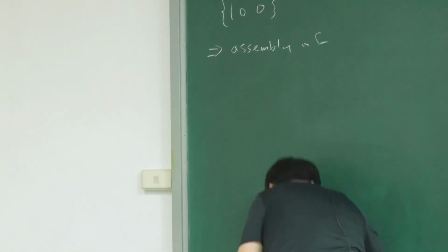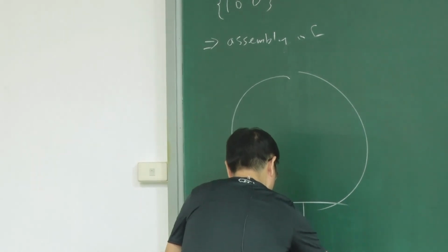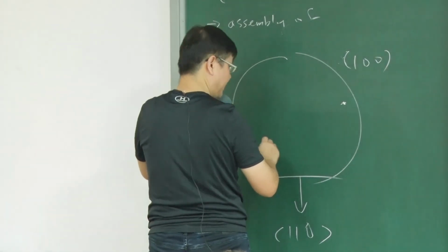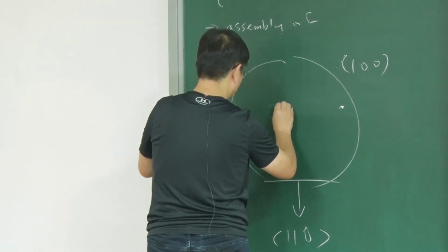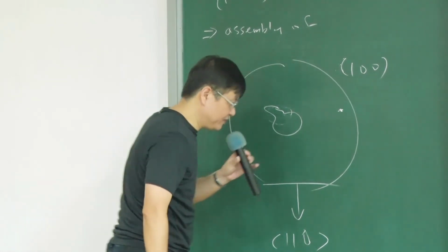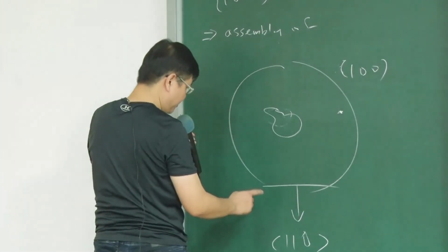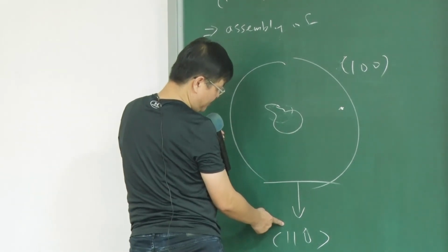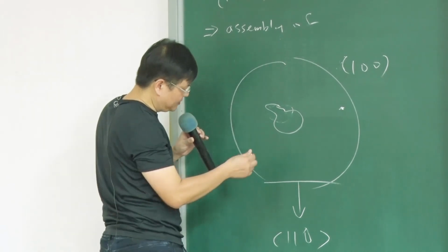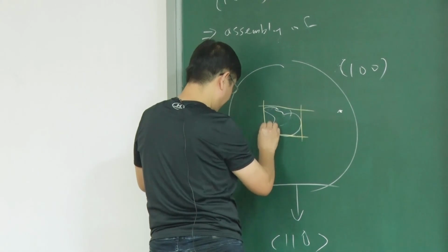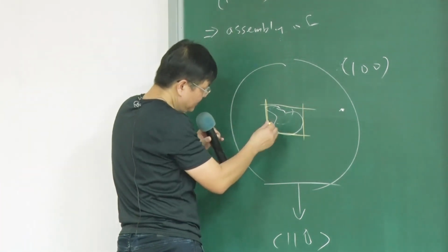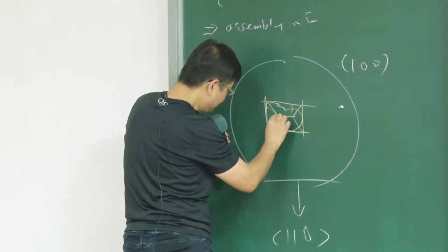For example, I give a homework: I want a 100 wafer, and I arbitrarily draw any kind of structure opening in the surface. What kind of final structure will we have? The final structure is very easy. We just draw 4 lines parallel to 110, because each line parallel to 110 means you have a 55-degree surface, and you can find the 111 plane. So you can draw 1, 2, 3, 4 boundary lines. Those boundary lines are the 110 boundary lines. When you incline 55 degrees, you find the final 111 plane.